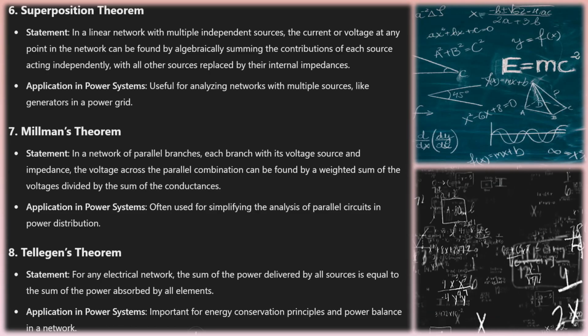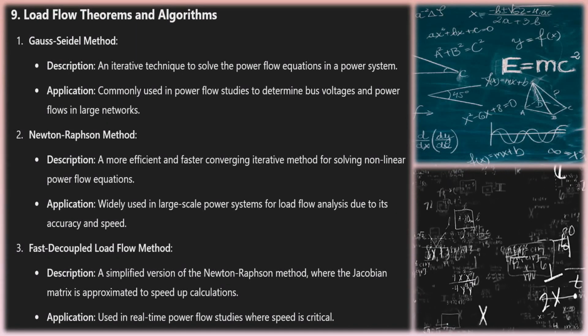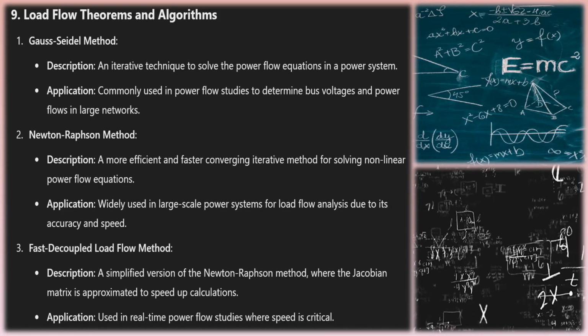Thevenin's theorem: any linear electrical network with voltage and current sources and resistances can be replaced at terminals A and B by an equivalent voltage source in series with a resistance. Application in power systems: helps simplify networks for easier analysis of power delivery, fault analysis, and load calculations.